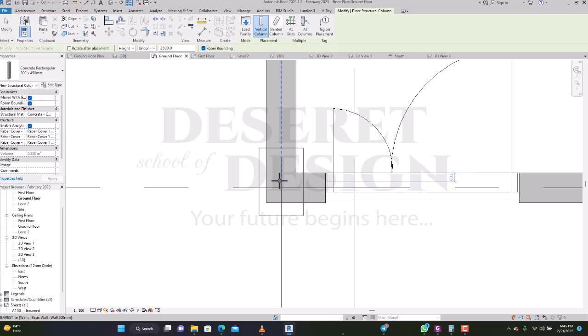But sir, I just selected the concrete triangle into the project, but it said some or all of the family files you selected cannot be loaded. You must choose family files of the category component. So how are you loading the thing? It's telling you the way you are loading the thing, it can't come. So you are loading the thing wrongly. Where did you go to load?